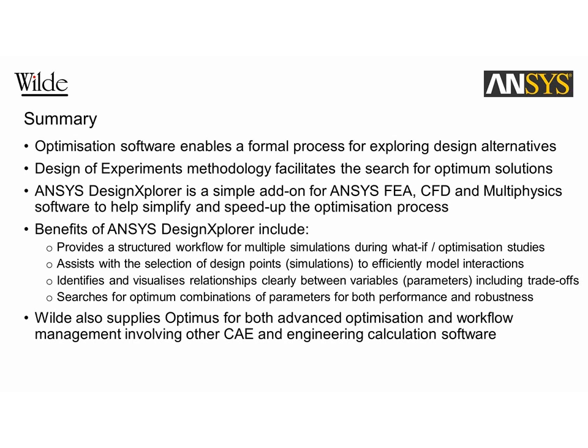So when we've been looking at the optimizations today, there's been a number of CFD or FEA simulations that have gone on in the background. DesignXplorer allows that to happen very quickly and efficiently from a user perspective. With the associativity built into ANSYS, we can automatically make geometric changes or parameter changes behind the scenes and essentially allow you to use DesignXplorer as an interface for driving those simulations.